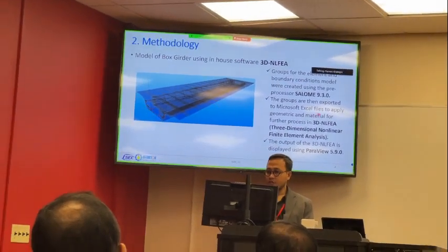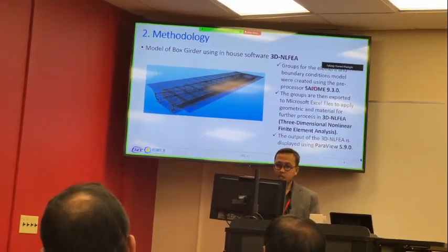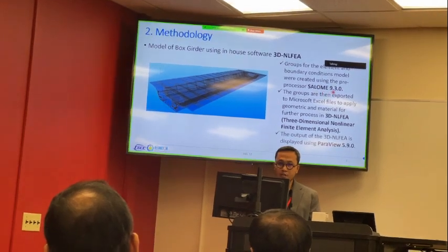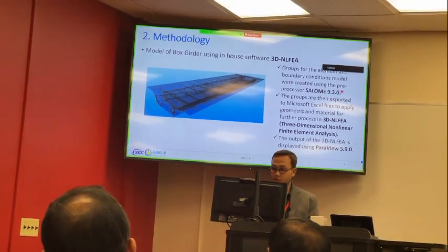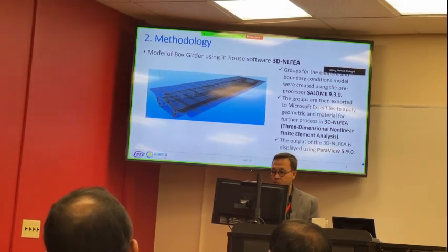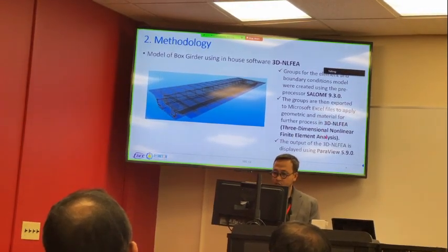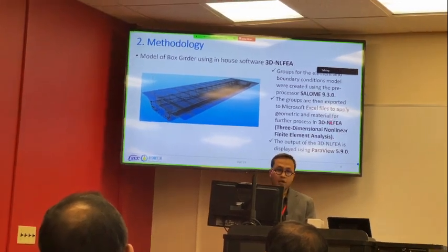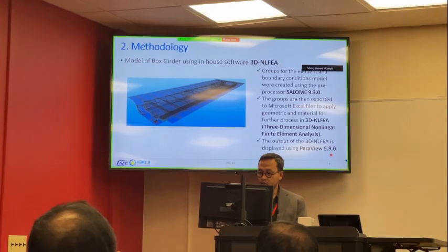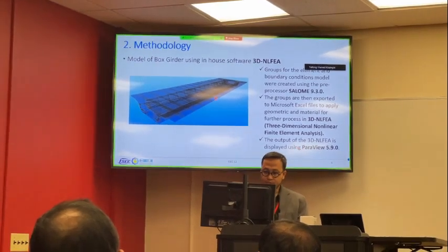To make this model, the group of elements and boundary conditions were created using Salome 9.3.0 software. For running this model, we use 3D nonlinear finite element analysis, and for the results of this modeling, we use ParaView 5.9.0.